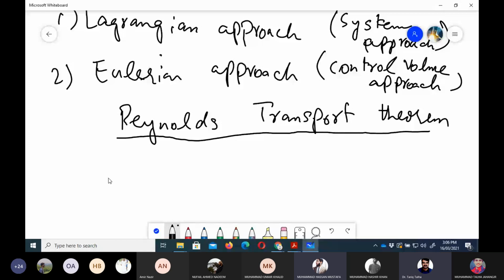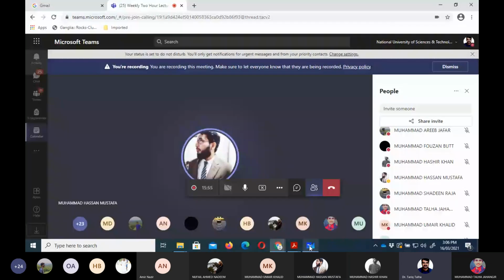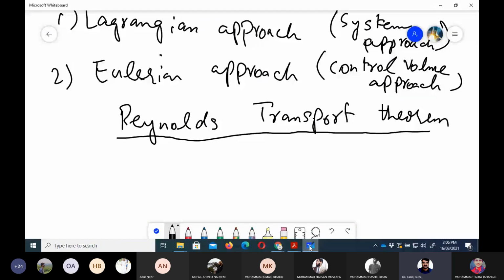Thank you very much, Hassan. I think your name is Hassan. Hassan Mustafa, sir. Okay, Hassan Mustafa, thank you very much for the clarification. It couldn't be any better. So you are absolutely right, because in the Lagrangian approach we are following the system, and in a system we have infinite particles. So it is basically impractical to follow each particle. Rather, we define a fixed volume in space, so that we can observe the particles which pass through that fixed space. So that is the Eulerian approach.